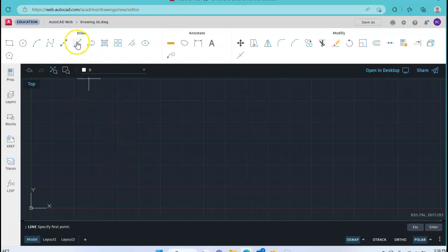So when I click my line tool, so I left click that, it comes down here to say specify the first point. We're going to say 0, 0. Notice I'm typing that in, 0, 0, and I'm going to hit enter. Again, that keying sequence where I have to physically type 0, 0 is different from the full version of AutoCAD where we would go 0, tab 0, enter. So just be aware of some of the differences between using these two versions. Once you catch on to both of them, it'll be pretty easy and you'll be a champ at drawing on all of these.